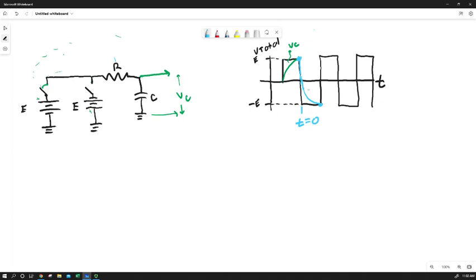That way I can look at my plotted experimental curve and verify my time constant with a measurement. Or I can look at a circuit where maybe I don't know R and C, identify the time constant, and figure out how I want to change R or C to adjust it.